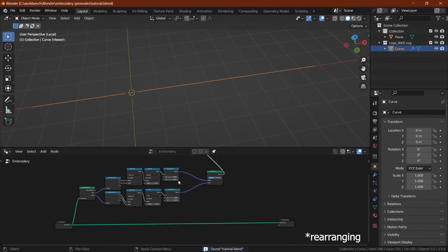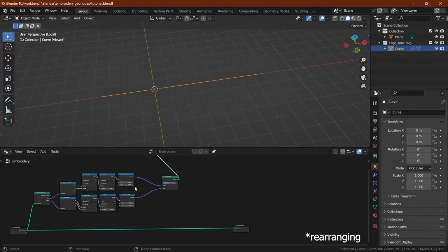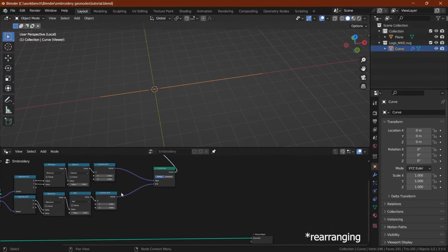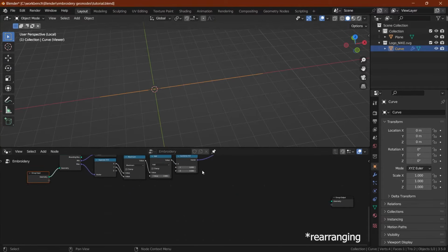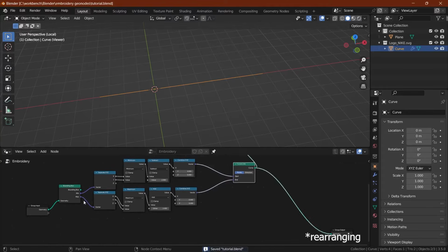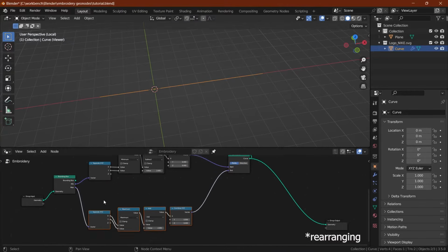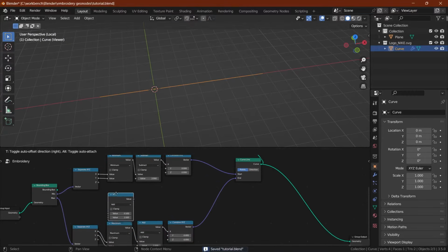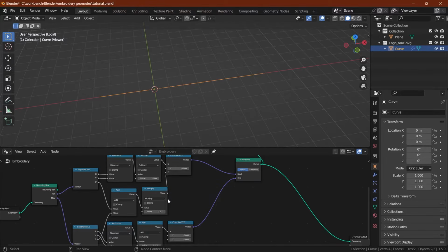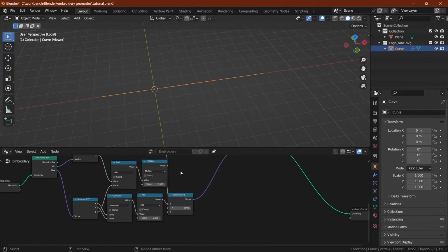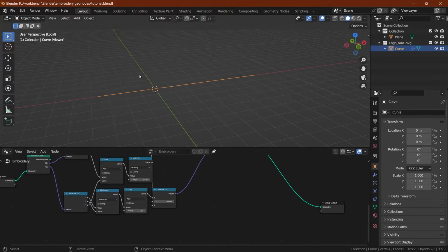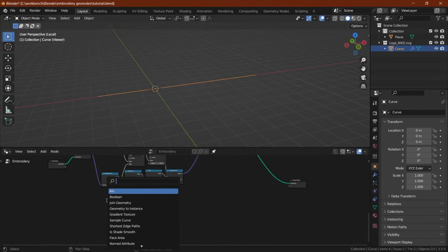In our case, the Z value is 0 since the logo is flat on the ground. But in a situation where the logo is tilted, so the start and end values of Z are not 0, we need to find the midpoint of the Z direction to pass the curve through it. Once this curve is set up, we'll now place points on it and spawn instances on it.